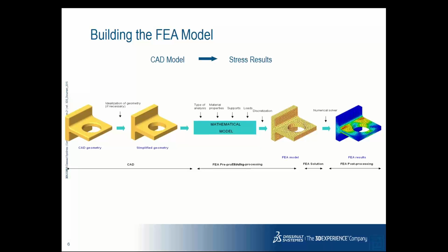If you have basic knowledge of strength of materials or mechanics, you will understand the reactions that are happening in the model, and accordingly, based on that knowledge, you can apply the boundary conditions to the model. In order to fix your geometry in space, you can apply the supports. In order to find the results, you apply the loads.